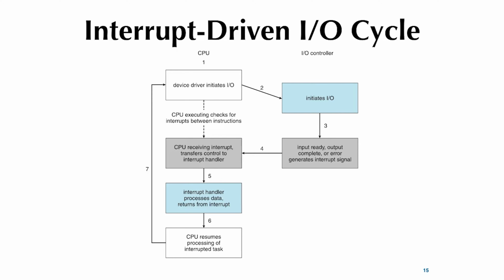Yeah. But it's just optimized by the speed of the processor. There is no other mechanism inside the CPU trying to keep track of the interrupts. Right. If you have another interrupt coming in while serving, there's no way it can tell, other than the explicit query. So most likely it's going to catch it. But if you're unlucky, yes, you just missed it. That the interrupt came and then you just missed it.